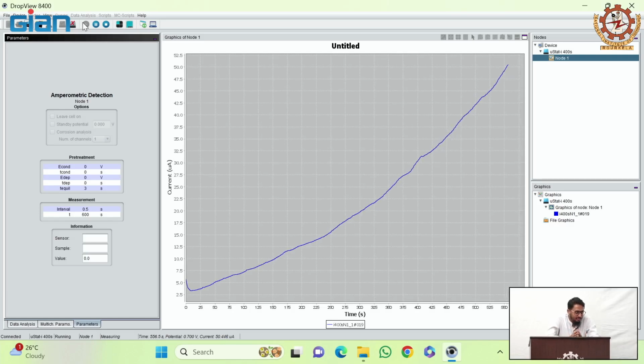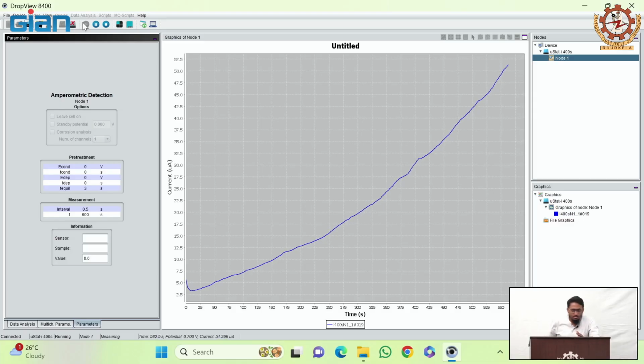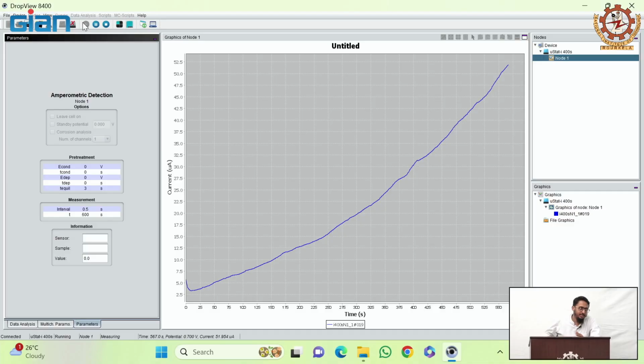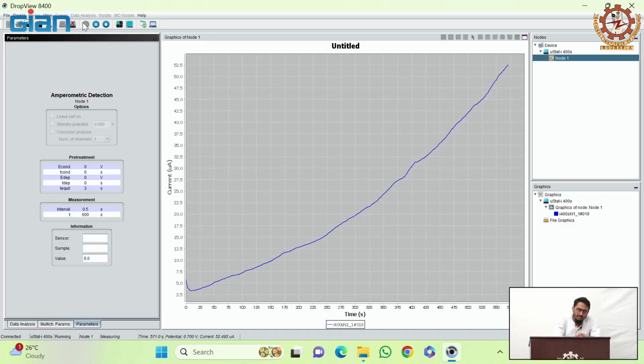Okay. So here we will be doing a 4-point calibration, right? 4 or 5-point, right? Yeah. So we'll be using 4 different known concentrations of glucose, and we'll measure the current. Then we draw a straight line, and then we find out the sensitivity. That is the last step.